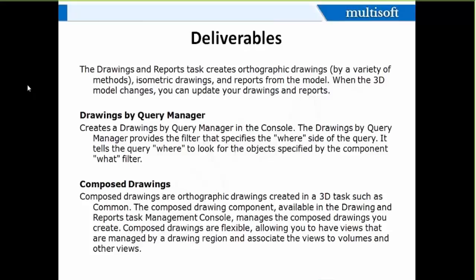In the same way, composite drawings, you can extract any type of GA drawings, general equipment drawings, equipment layout, plot plans, key plans for all disciplines, electrical cable layout, structural framing sections. Okay, any type of drawings you can extract in the 2D. And also the default drawing generator is .sha, Smart Sketch 2D editor. You can save the drawing into .dwg for AutoCAD, .dgn also you can select for your MicroStation. Okay, and also you can save it as a PDF or image, any of the formats.